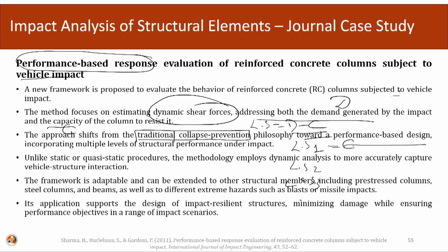So, this might be the limit state at cracking, this might be the limit state at elastic only response, this might be at yield of steel, this might be at crushing of the concrete. So, different limit state functions we can formulate.